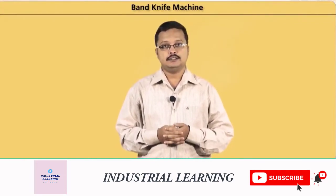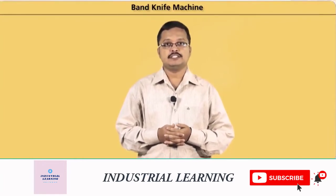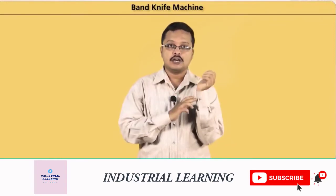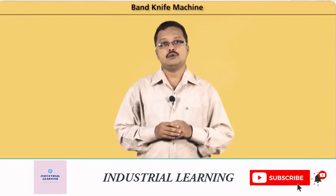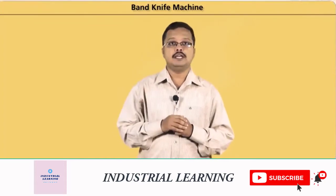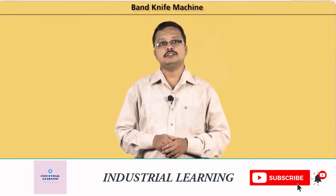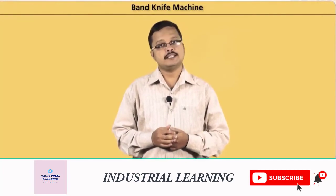One edge of the blade is sharpened and the blade is narrower than the straight knife, which is the greatest advantage of this machine. It gives accurate cuts for small parts such as collars, curves and pockets, as the turning of the block on a narrower blade disrupts the plies less than the wider blade of a straight knife machine. When using this machine, space has to be left around the garment parts during planning the marker. For small parts, a template can be used as a guide.